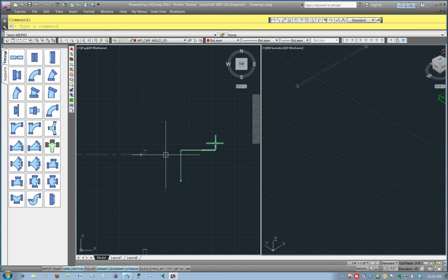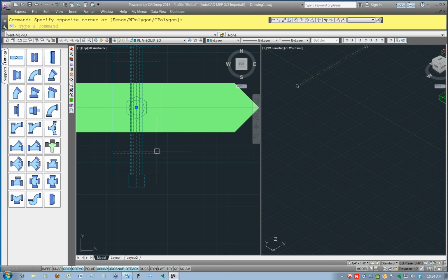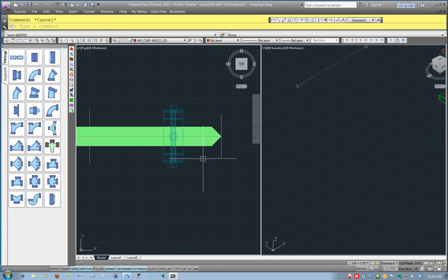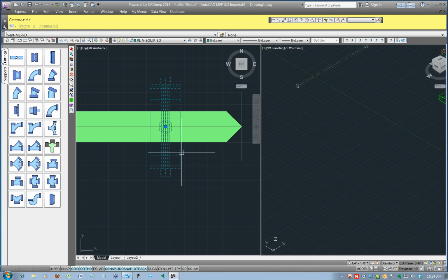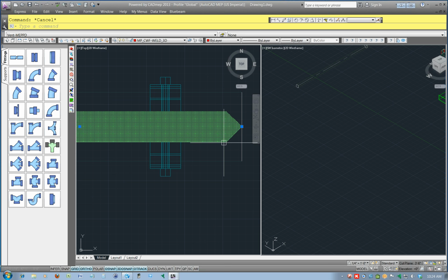There is a way. I'm not familiar. They showed me a little bit, but you can create buttons where you have multiple pieces inside of one button, and they will fill in together. Like if you need to place a copper or a PVC to copper fitting, and then a valve, and then another PVC to copper fitting, and then go back to PVC again. There's assemblies you can create, and there's a help file inside of those resources I gave you, which, if you need to create assemblies, should teach you how.